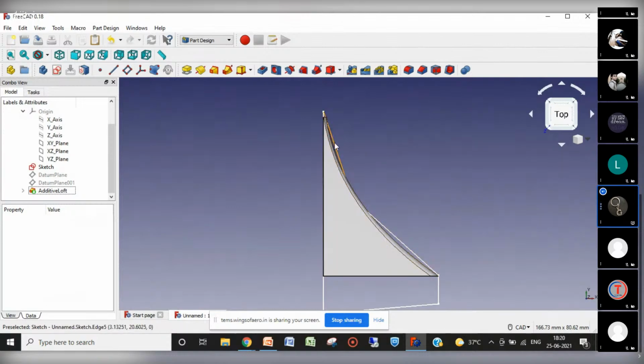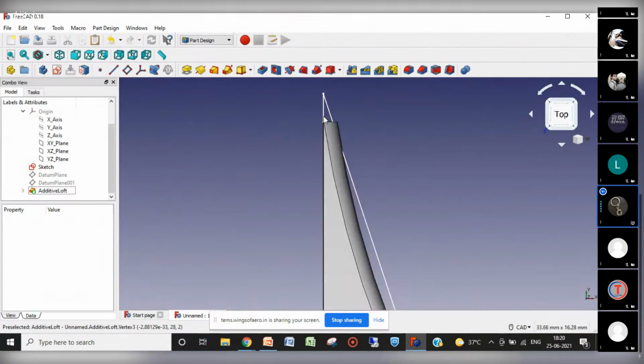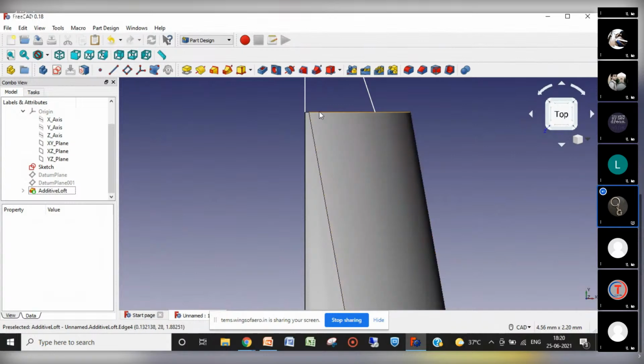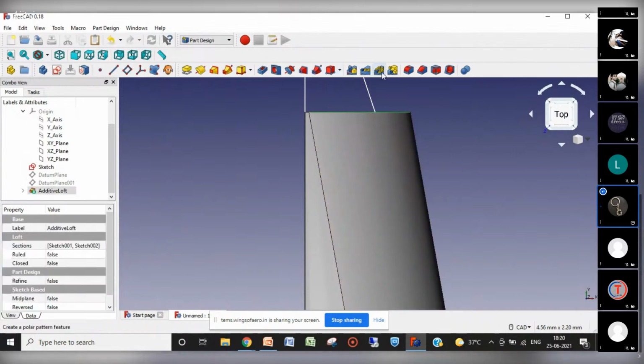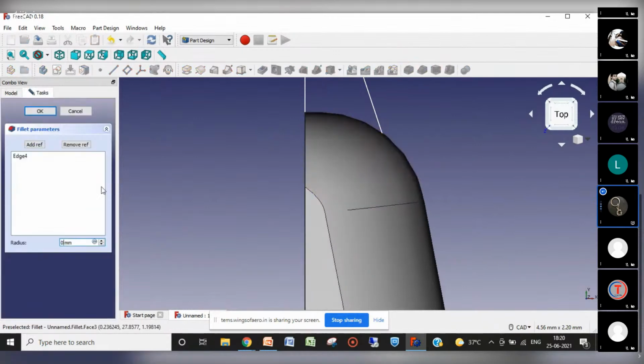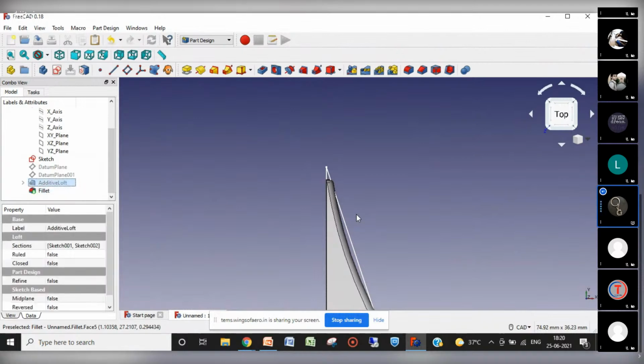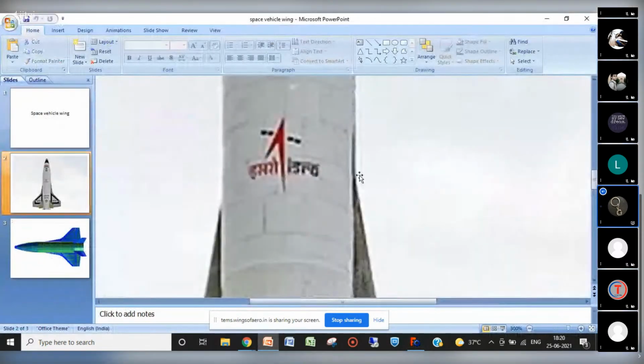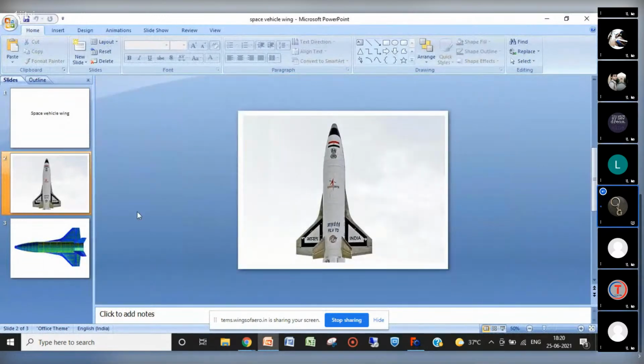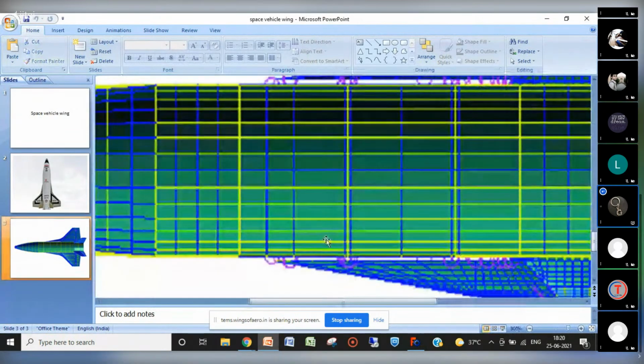Which we have made for the reference. It should be much straighter. If we had a section in between, it would be straighter, and one section here, it would be much more perfect. That's why I said if you want, you can take those sections. Here you can choose this and apply a fillet of 0.25. Okay, as it is not that sharp, you can see here. Also, in this figure you can see, once you connect it there, it is not that sharp. It has some curve there.